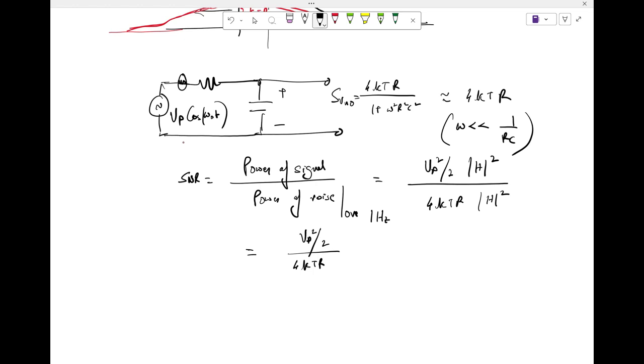But I think he pointed out one important point. If I reduce R, right? So right now it seems like an easy fix. I reduce R, but let's say I want to keep the bandwidth fixed. So reducing R and keeping the bandwidth fixed would mean, what should I do? I have to increase C. Correct? Makes sense, right? So I have to increase C.